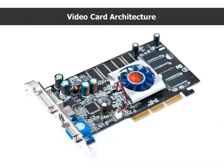So let's actually drill down into the individual components that typically will compose the video card. Now you actually see a very high-end video card here. The first thing to keep in mind is the GPU, or graphics processing unit. This is a dedicated onboard video processor so that the system CPU doesn't have to be taxed. It's optimized for acceleration for 3D or 2D graphics rendering, and again, it takes pressure off of the CPU.